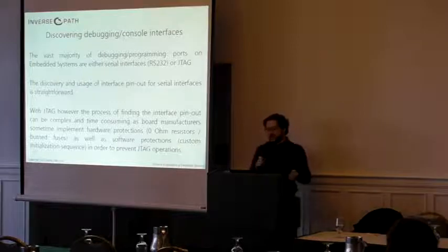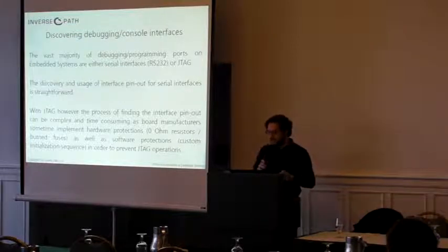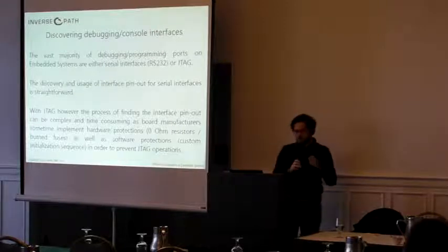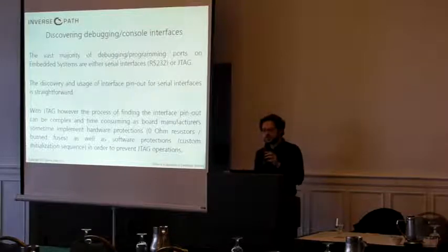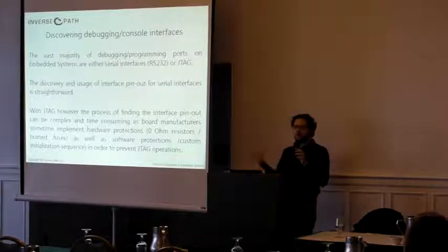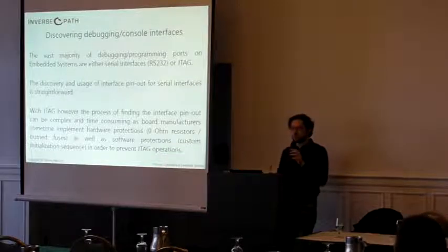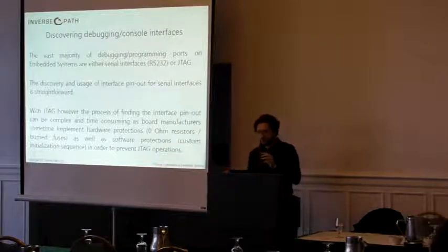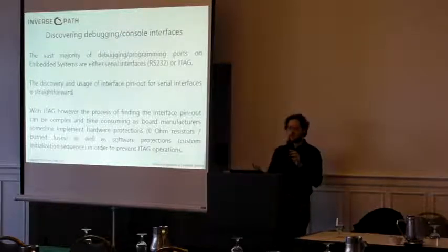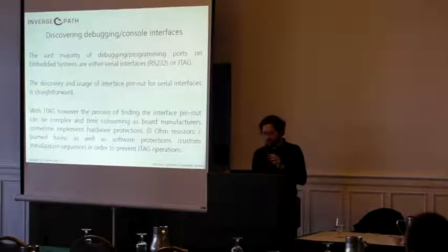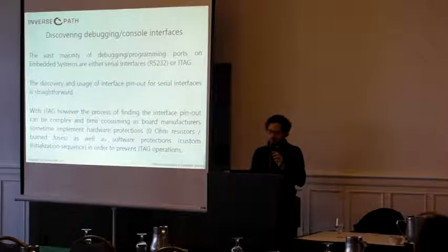Before getting into details, the first thing that pops up when you have to deal with this kind of system is that you usually have to gain knowledge about the system that you're targeting, which means you have to find some kind of debugging access, either to debug what the CPU is doing or to dump the memory and so on. The most available debugging or access interfaces are serial interfaces, which you can find on many devices, or JTAG ports. Some of them can be found really easily, and some are a bit more difficult to find, especially the JTAG ones.